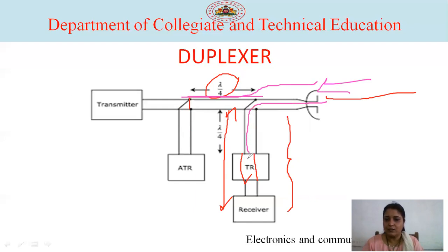Now the echo signal will be entering here. Now there is no short circuit here. Therefore freely it will enter through this switch to the receiver section here. Therefore during the receiving time, the transmitter section is disconnected here. Only the signal is reaching towards the receiver block. Now this is the explanation for this.